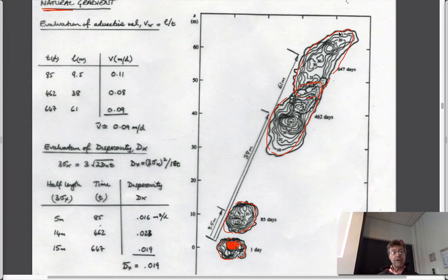But this is a shallow aquifer where you can basically put a steel, 1/10 of an inch diameter capillary tube physically into the ground and suck some water out of it to be able to get a concentration that then you put in a GC to be able to measure the relative concentration, or ICP-MS, to be able to measure concentrations, and then you plot those. And so what can we do with that?